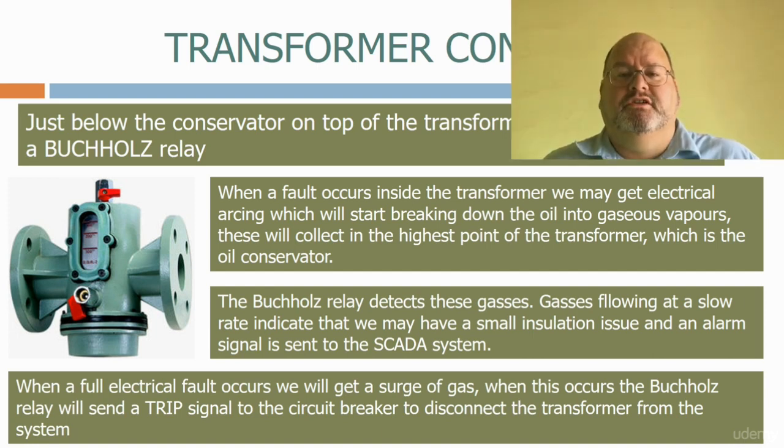High voltage networks use some of the most advanced communication and protection systems to quickly identify and clear any faults. But we always need a few old-fashioned mechanical devices in the system to provide a last resort backup when things go wrong. The Buchholz relay is one such device. We know that if a fault occurs inside the transformer, some gas will be generated in the oil. The bigger the fault, the more gas will be created, so it's a very reliable indicator of something going wrong inside the transformer.